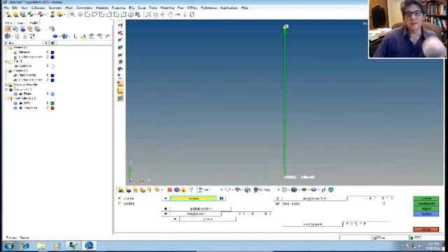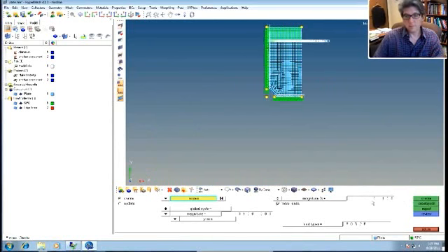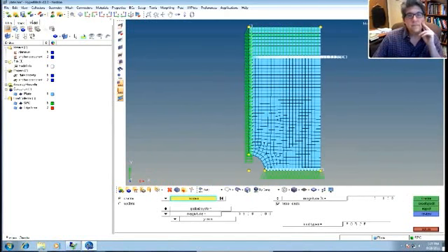Oops, they're really big. Let's scale them by 1. And they're still pretty big. 0.1. Now look. All right, that looks good. They're all in there. The only problem I have now is I forgot to change the active load collector to edge force, so it created them in SPC.